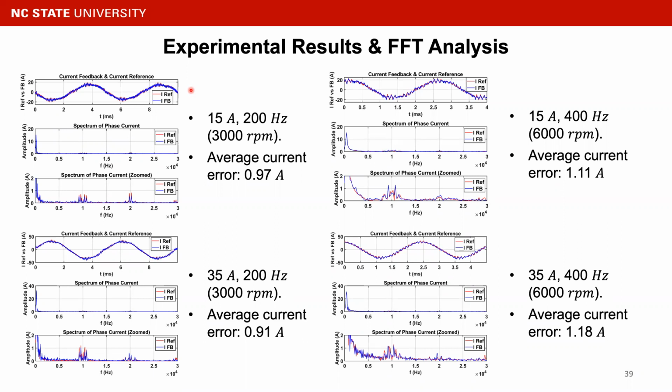And then we have another conventional low bandwidth voltage sensor to sample the actual voltage level of our DC bus. By multiplying the logic level with the sampled voltage level of the DC bus, we can reconstruct our PWM voltage. So basically we have a 2-step process here for the voltage sampling.